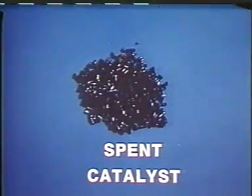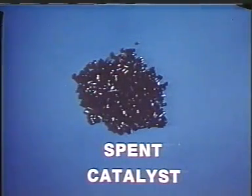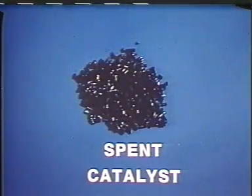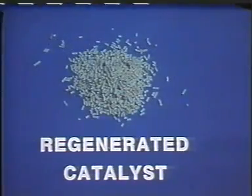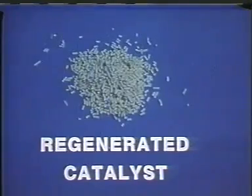During the reforming process, coke, or carbon, is gradually deposited on the catalyst. As this happens, the catalyst's ability to reform the feed declines, so eventually the coke must be removed. The catalyst is cleaned or regenerated by burning the coke off its surface.